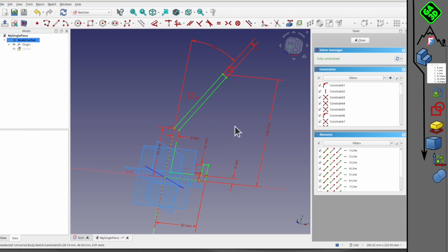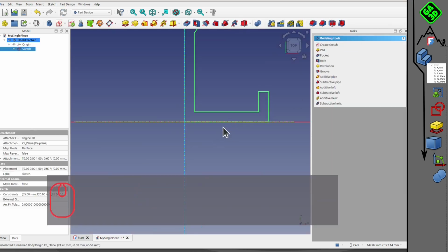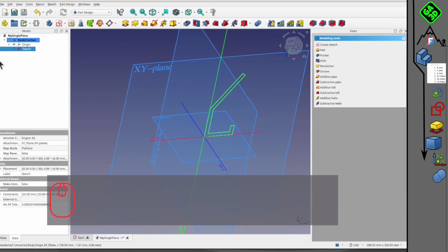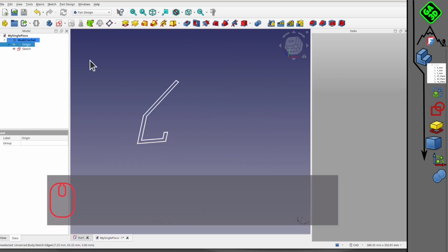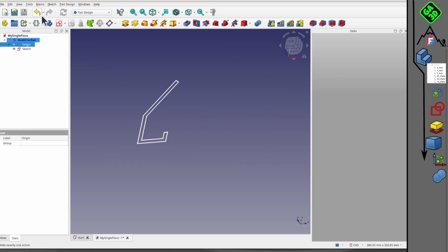So we're back on our workflow. We created the file, a body in the file, and a sketch based on the marker. And then this sketch, to create volume of material, we'll just extrude it with the pad tool. I want it to be 15 mm long. There you go. So the base of my hook is already done.